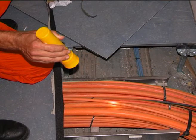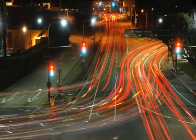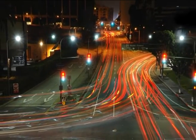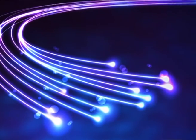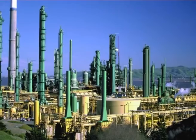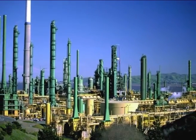Attenuation is significantly lower for optical fiber cables. Optical fiber systems are not affected by external electromagnetic fields. Fewer repeaters mean lower cost and fewer sources of error. Running cost of optical fibers is less than coaxial cables. Copper systems consume far more electrical power than optical fiber to carry the signals. Optical fibers are immune to electromagnetic interference from radio signals, lightning, etc. They can be easily routed safely through explosive or flammable atmospheres, for example, petrochemical industries.